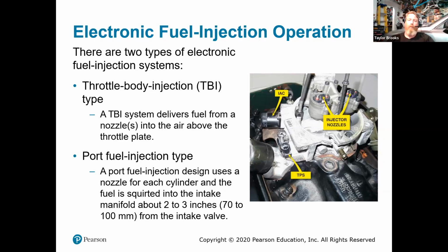Now, I have made a change to my truck. When I first built the motor, I was running a dual plane intake manifold, very similar to what most street driven carbureted V8 engines require. A dual plane intake manifold has two segregated paths of incoming air after the carburetor, and the idea is each pathway allows scavenging pulses to benefit drawing in the fuel and air mixture from the cam overlap.